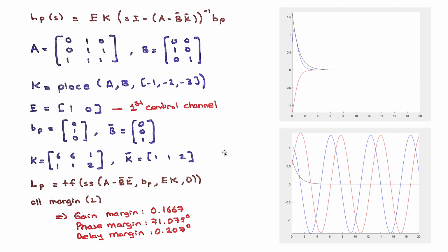how these margins help us to assess resilience and robustness of our control channels. And for the first control channel in that regard, look here, we are trying to stabilize an unstable system. We have a control gain. Our gain margin is good, actually better than the previous example. Delay margin, it is okay. If you have more than 0.207 seconds of delay when you are applying control signals, it is not feasible, so you need to retune your controller. If not, these are good phase and delay margins.